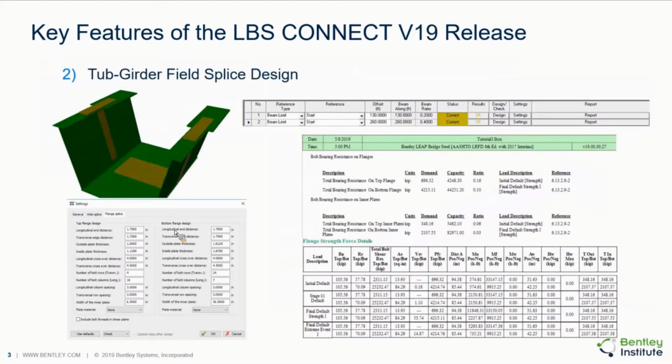Let me move on. The top girder field splice design was the biggest analytical enhancement we added for Lippert Steel. Lippert Steel users already know that we were supporting I-girder field splice design, but top girder field splice design was not implemented yet.